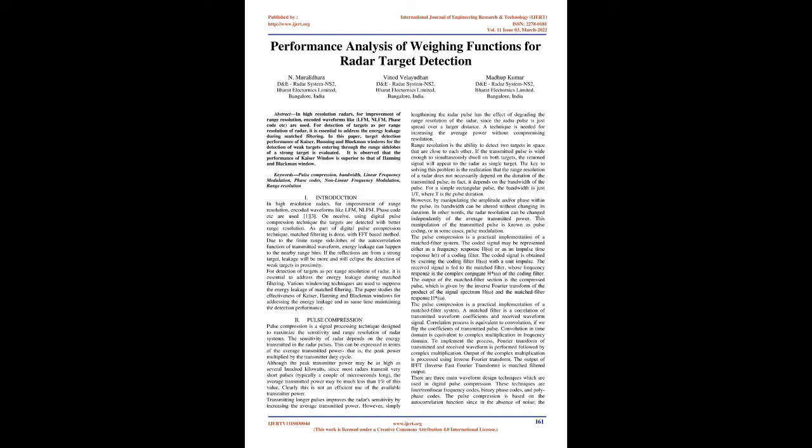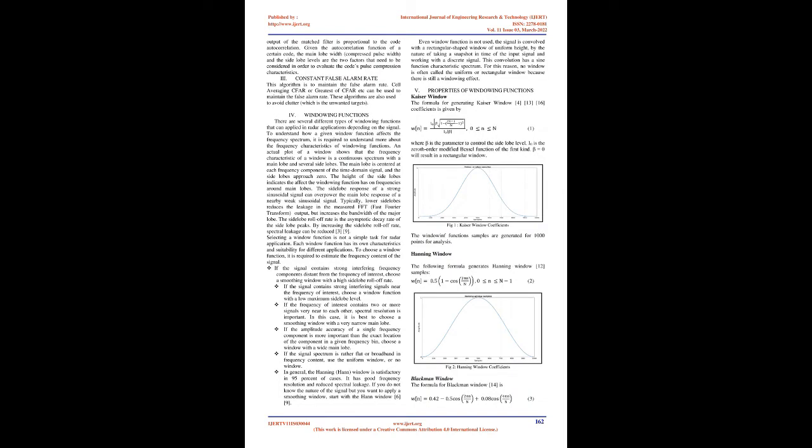Transmitting longer pulses improves the radar's sensitivity by increasing the average transmitted power. However, simply lengthening the radar pulse has the effect of degrading the range resolution of the radar, since the radio pulse is just spread over a larger distance. A technique is needed for increasing the average power without compromising resolution.